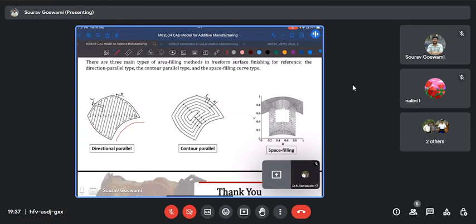And space filling is a new method where we fill the surface based on the final geometry itself. So there is no predetermined strategy or predetermined contour which we simply recreate or offset, or any similarity between the contours. We keep going in 3D space based on the final geometry that we want. So I also have an example video of a space filling technique for something called direct writing, which we'll see in the upcoming hour.